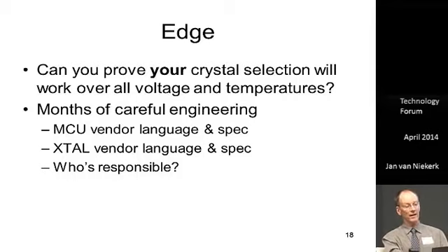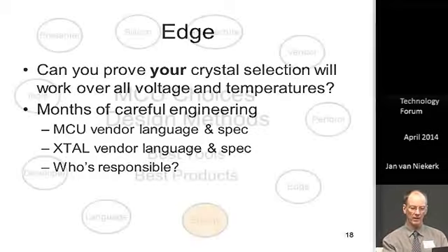So be careful. And actually, since I've been through that process, I just want to make the point that making sure that a crystal and the microcontroller actually work together well is literally months of careful engineering, because you really have to understand the spec of the crystal maker, and you have to understand the spec of the microcontroller maker, and the right specs are sometimes very difficult to get out of those two parties. And then the other thing is, if something goes wrong, who's responsible?